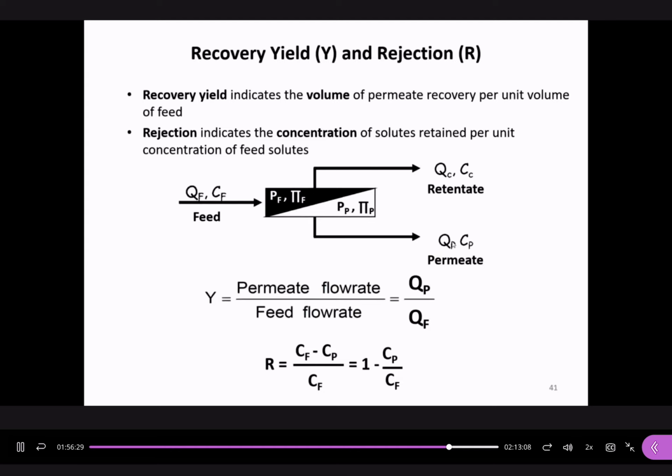That is the pressure. Let me emphasize again. That's the pressure you have to overcome. You have to apply a pressure higher than that for seawater desalination. So in reality, we applied 50, 60, sometimes even higher pressure, much higher than osmotic pressure, to drive the process.